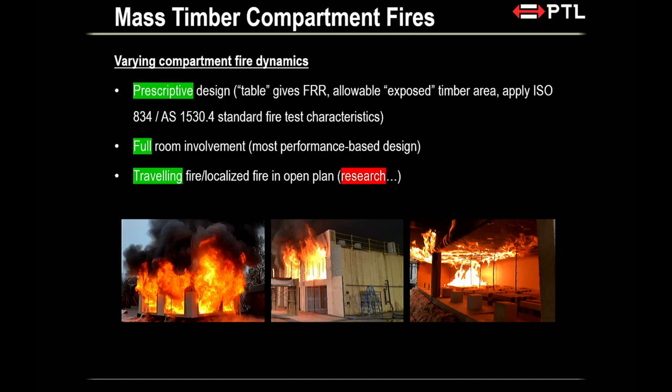I figure out what's the ventilation. This one is very well ventilated. You can see a lot of opening. That one might not be so well ventilated. They will have different char depth, okay? And I will need to pass that char depth information to you for you to complete your structural design, because you might have a column in there, you might have a beam in there, you might have a wall in there, right?